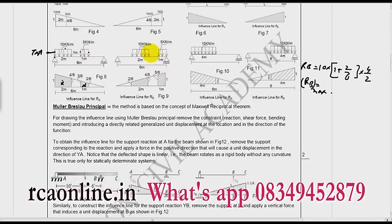How to find RB? For RB, what will be the case? The 5 kilonewton per meter load's head will be at B, its tail is below. Then I will have the 10 kilonewton per meter load and then the tail at this point. In this condition, I will have the maximum value of RB. How to find the value of RB? It is simple. Multiply this area by 5, multiply this area by 10. That will give you the value of RB.